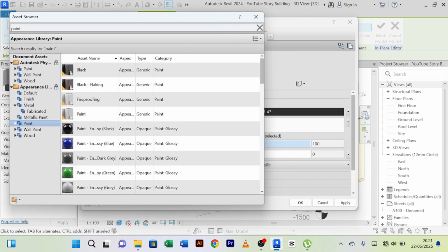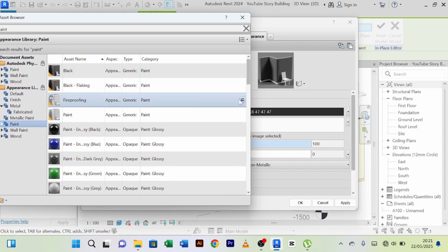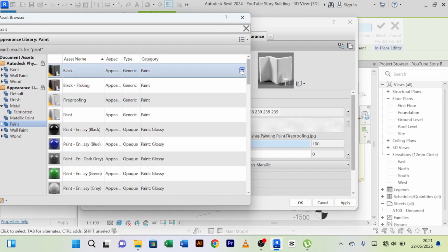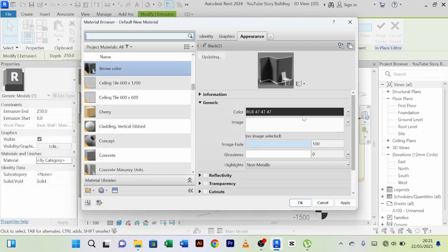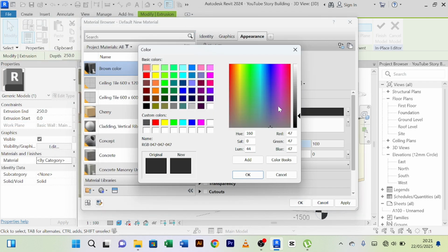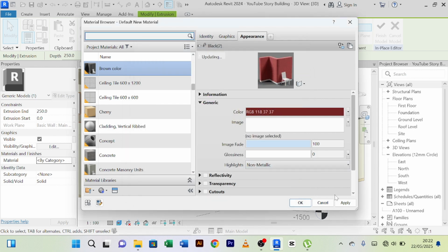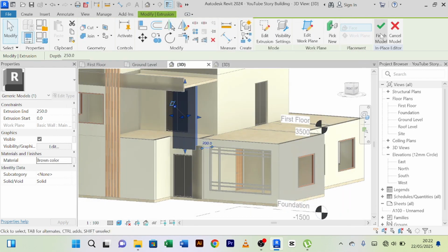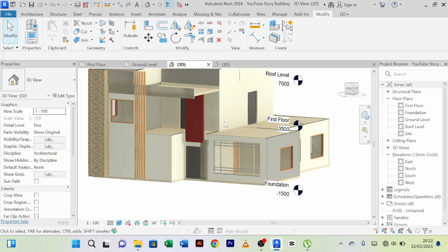However, you see this thing is sitting almost on the door. That means we need to remove the door from it. So we shall edit in place. After selecting it, you edit it in place. You select it again, you edit extrusion. Then you have to take away the door. So we shall offset this. However, I can just pick this and draw something that is not really so close to the door, so that the door can be on its own.